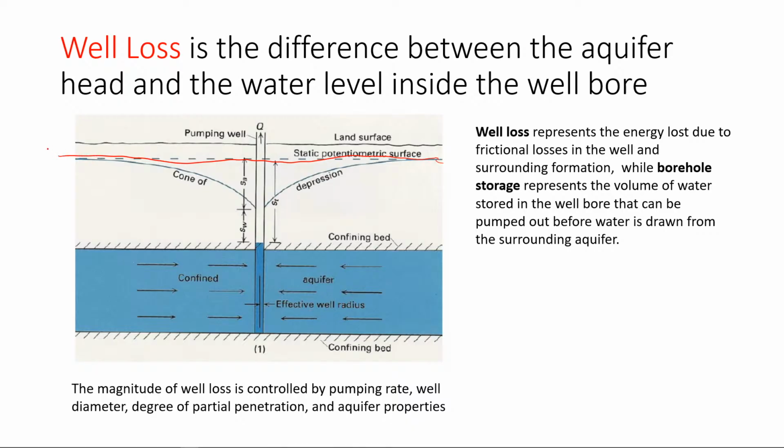And then once you start pumping, your head will drop to here, yeah? But you see the head in the well is much less than, like you have much more drawdown in your well than in this cone of depression. And this is called well loss. So here you have an extra energy loss, and this extra energy loss could be due to several factors.